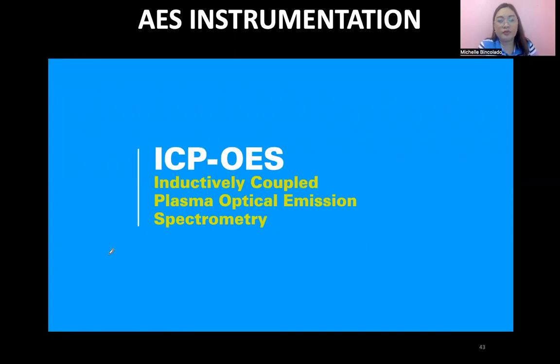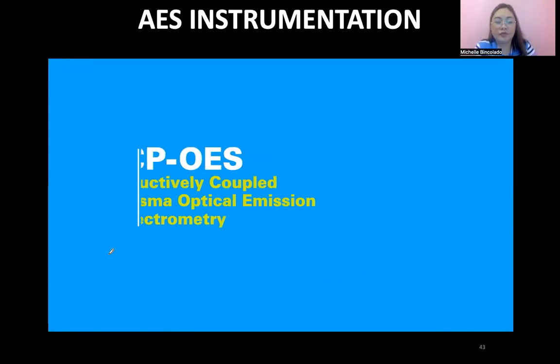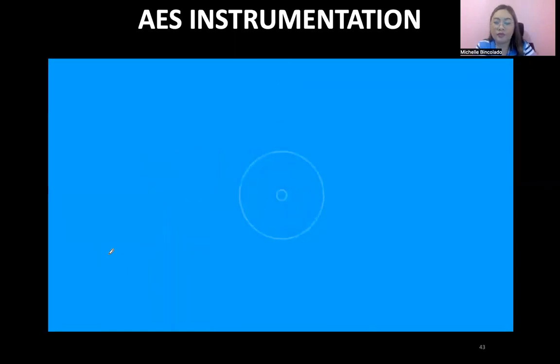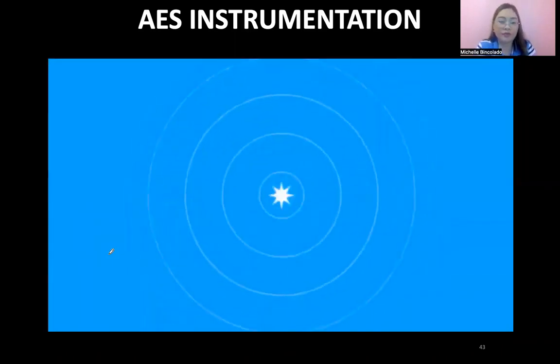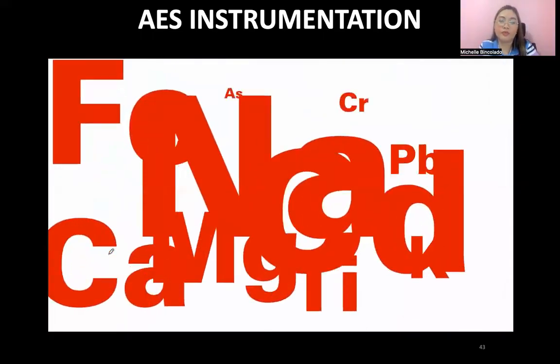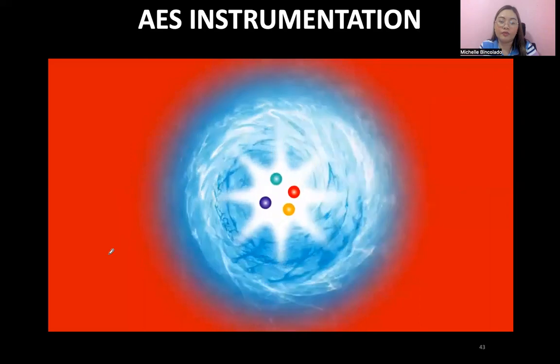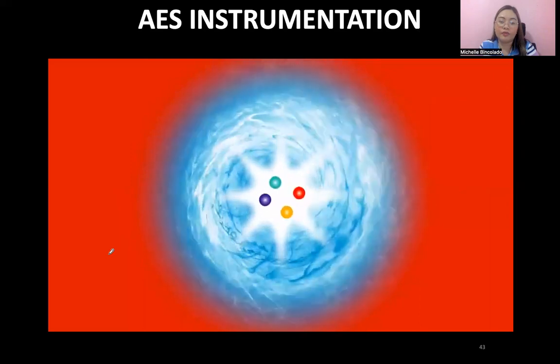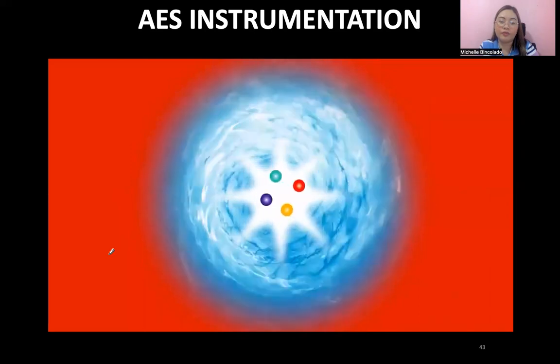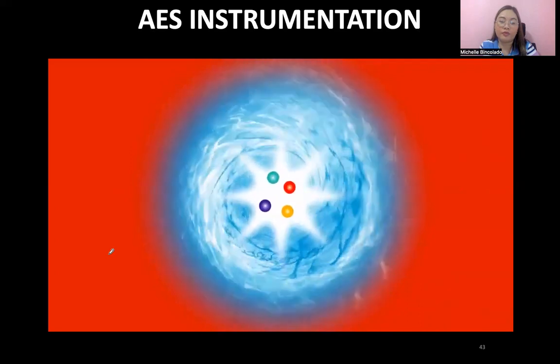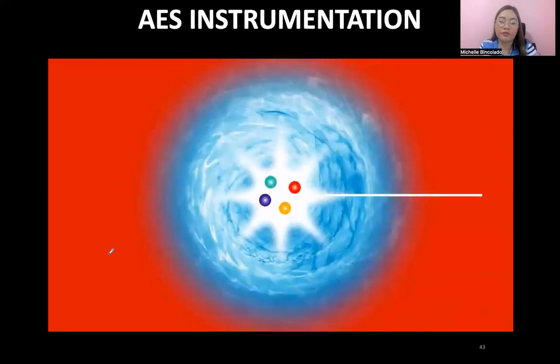What's the job of an ICP OES analyzer? To see what things are made of. To do so, fundamentally, the analyzer turns liquid into light and light into answers. To find out exactly what chemical elements are in a liquid sample, the analyzer runs it through an extremely hot plasma. As the heat excites the atoms and ions of the sample elements, they emit light.